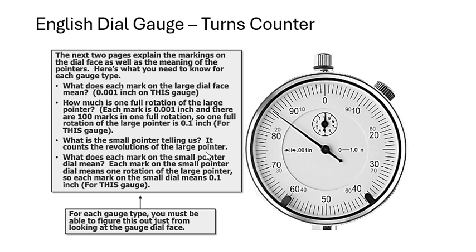You need the gauge block. We know the exact height of the gauge stack because it is printed on the gauge blocks. So you're going to add them up, and then you're going to set 0 off the top surface of your gauge. Then you're going to swap your gauge block stack with the object of your interest to measure, and then you're going to do the math, either subtract or add. If it drops, then you subtract. If it rises on the other side of the 0, you're going to add that measurement to the sum of your gauge stack. So you get an idea of how to use this dial gauge.